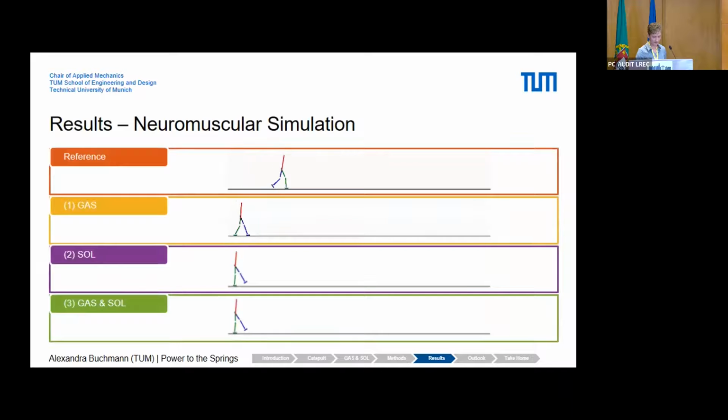Once I click on it here, you see that all the guys are still able to walk, and we did no adaptations. We just replaced the muscles and that's all. And I think that's pretty surprising. We, of course, did detailed analysis on metabolic energy consumption and on how the joints move, and compared this to a natural walking gait of a human. And we see it's really possible to walk without any active actuation at the ankle joint, purely passive.